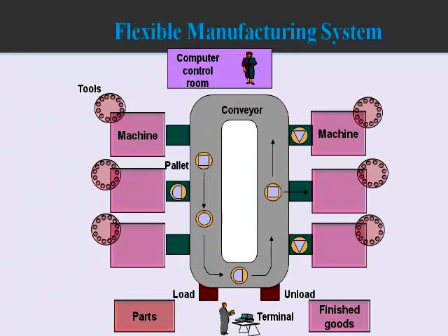You see this flexible manufacturing system. The workpieces are transported from the loading station to the machines as per the process sequence, and the required CNC programs are downloaded as per the movement of the parts among these machines. The part programs are downloaded and the parts are routed as and when a particular part reaches a machine and is placed on it with the help of pallets.